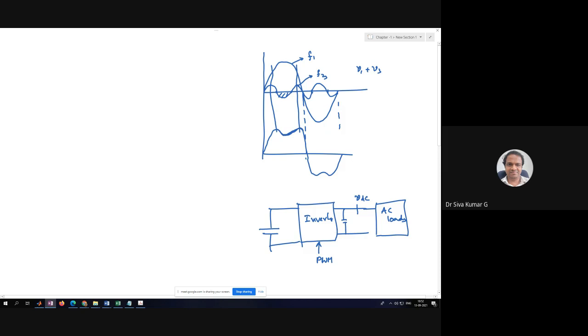The harmonics present on the AC side of an inverter operating with the PWM scheme are in the order of the switching frequency component, but not of the fundamental frequency. Because of that, we will be having interharmonics in a system.